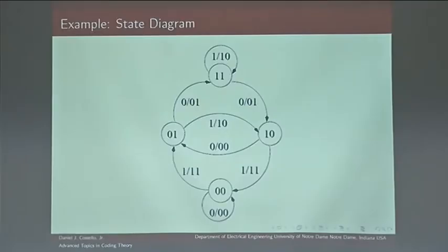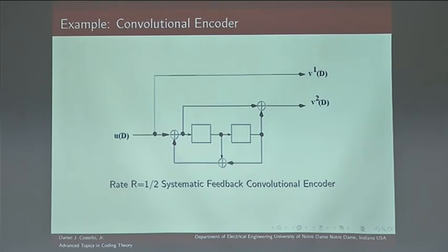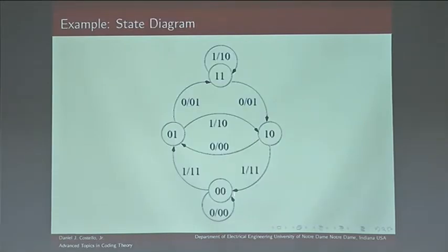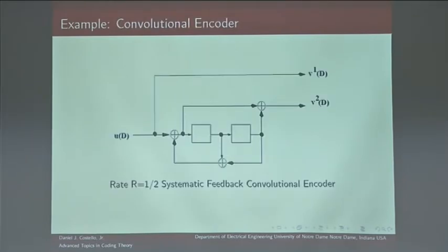So here's the state diagram. Let's see if we can figure it out. We won't do the whole thing, but it's going to be a little different and a little trickier than the other one. So we'll start with the easiest case, 0, 0. We put a 0 in. Of course, we're always going to get the self loop around the 0 state, 0 in with 2 0 outs, and we stay in the 0 state. Now what if we put a 1 in?